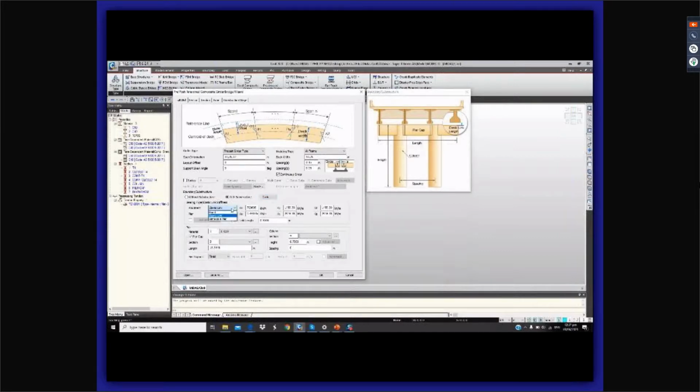For the abutment, you can choose if the support is fixed, elastic link, or the same as pier. So we'll be having the abutment as fixed. And then for the pier, let's use the elastic link. Then for the stiffness in x direction, let's input 1.5 kilonewton per meter raised to 6. And then for ky, stiffness in y direction, 3000. And the stiffness in z direction 3000 as well. Then the elastic length, let's reduce it to 2.3 meters.